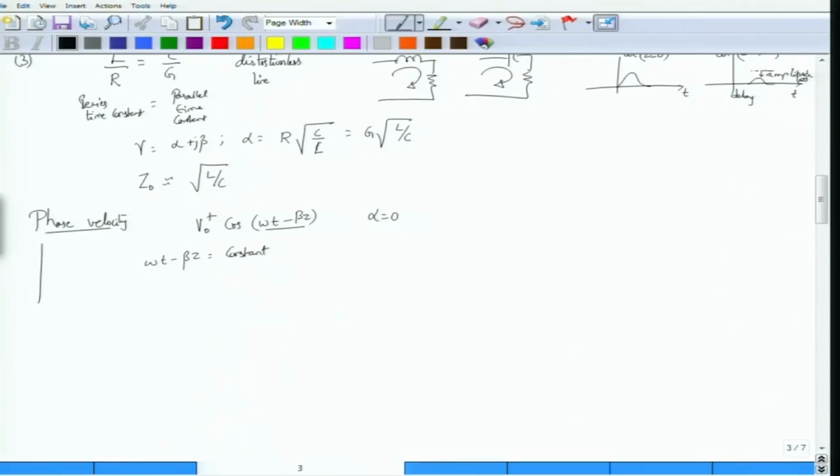So you have your waves which are going as a cos omega t. So you have this wave, and if you pick a particular point which is characterized by, so this has to be both z and t, I am just showing it as a function of z. So if you pick a particular point at which this argument omega t minus beta z is constant, and then look at how this particular constant point actually moves in time, then the velocity with which it moves will give you the phase velocity, because this would be the phase with respect to some reference phase, and what you are looking at is how this phase itself is changing as t and z increase.